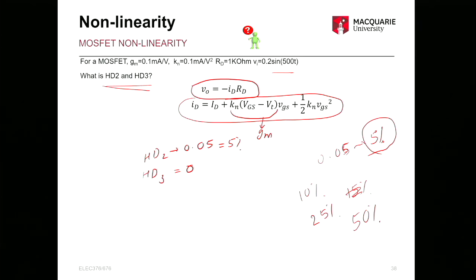It is usually referred to as 3 dB frequency because negative is understood, because positive makes no sense, because the mid-band gain is the maximum gain you can have, and it tapers off on both ends, right? So this is 3 dB and 3 dB. It was the same question as in the lab, so if you have done the lab and found the 3 dB frequency, it's quite easy, you know exactly what 3 dB is.